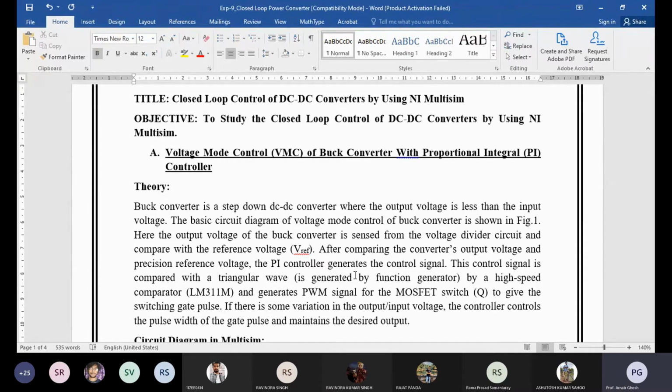If you are using a DC motor as a load of the 4-quadrant chopper, in that case if you vary the input voltage, your load voltage also varies. If you vary the duty cycle, your load output average voltage also will vary. That means the input of the motor load also will vary. Okay, if the input of the motor load varies, the motor has 3 modes of operation. Normally in speed control there are 3 methods: armature voltage control, another one is field control. Now I am only focused on the input voltage control or armature voltage control.